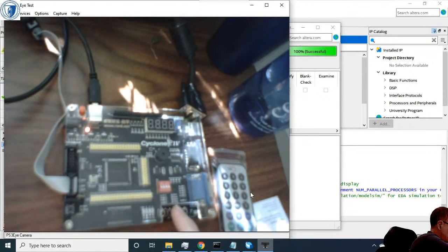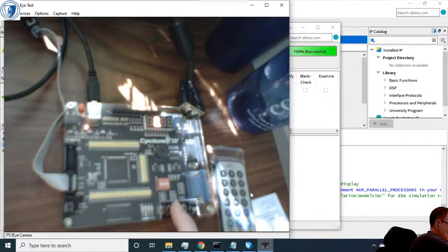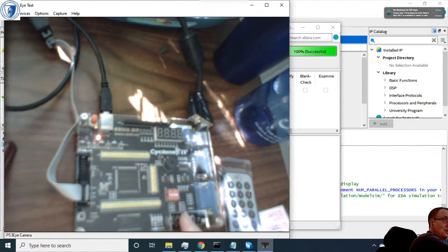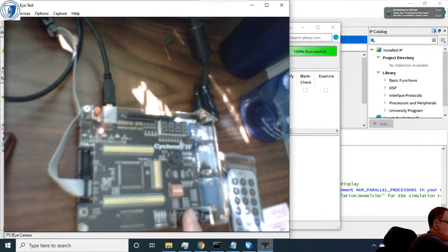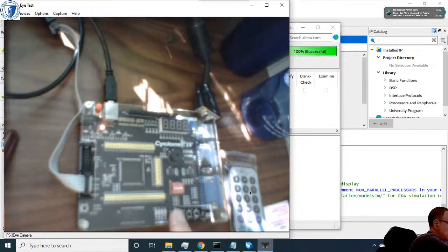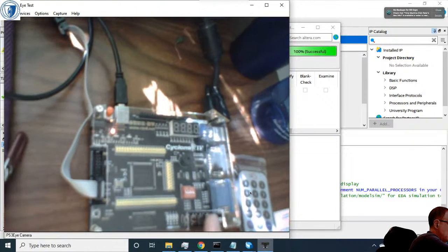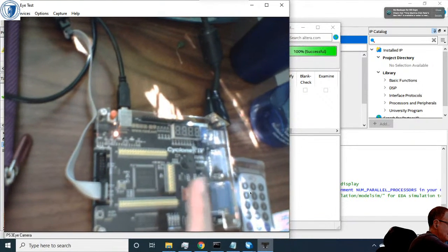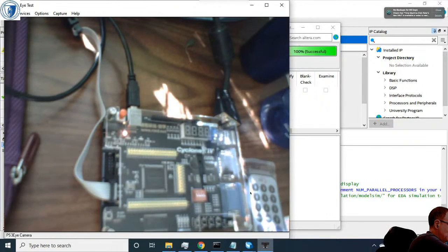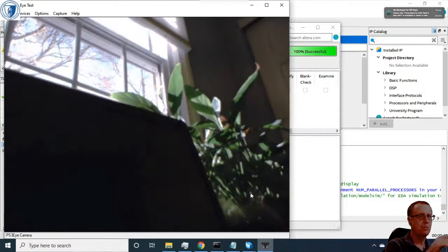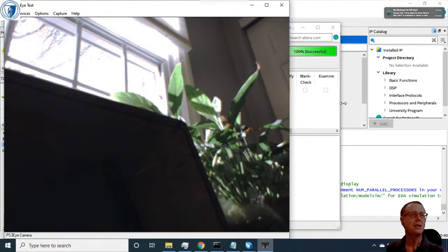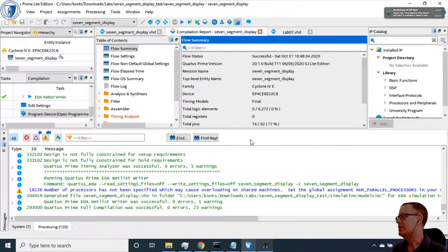And here I'm pressing the second right hand and the second left hand one is displaying. So I probably want to swap around the orders there of the buttons that I'm using compared with the displays. But what you might remember from one of the other labs is that those buttons are active low,